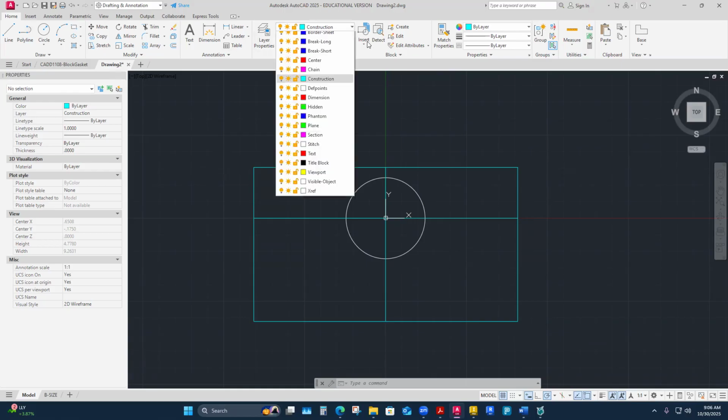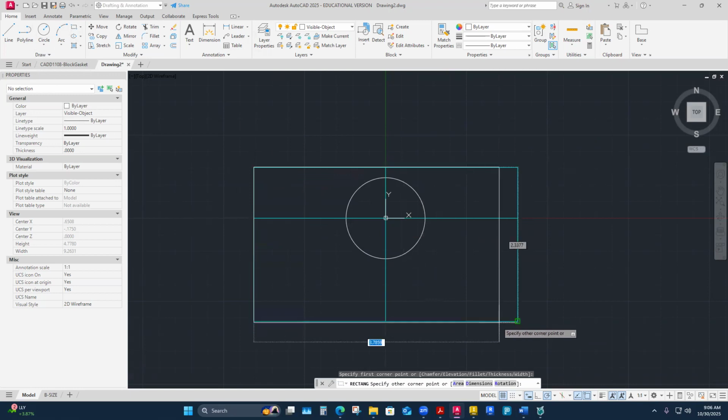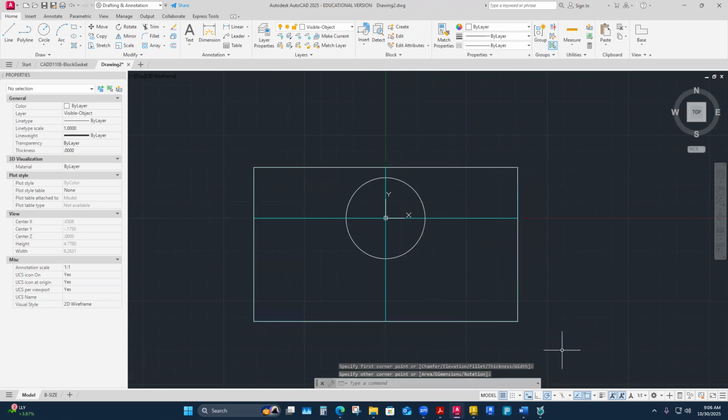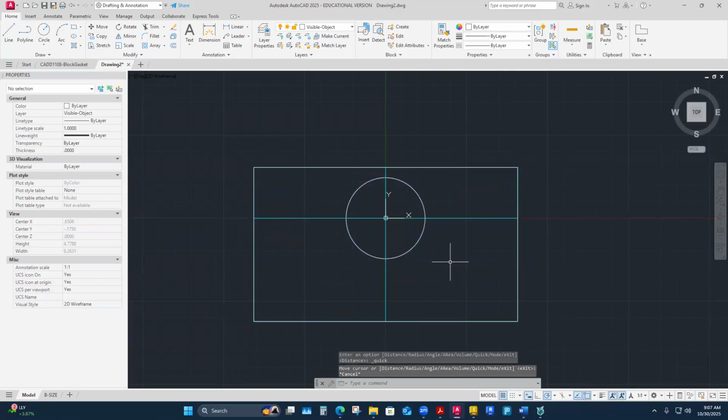So I'm going to switch over and trace that over with probably just a rectangle. Draw a rectangle, snap it to that. This is one you might want to keep track of. As you're piecing stuff together, it is helpful to keep track with something to make sure you haven't fat fingered a dimension somewhere and ended up with the wrong dimension, and you wouldn't know until you start to dimension stuff out that you've slightly missed. So just keep track as you build it.